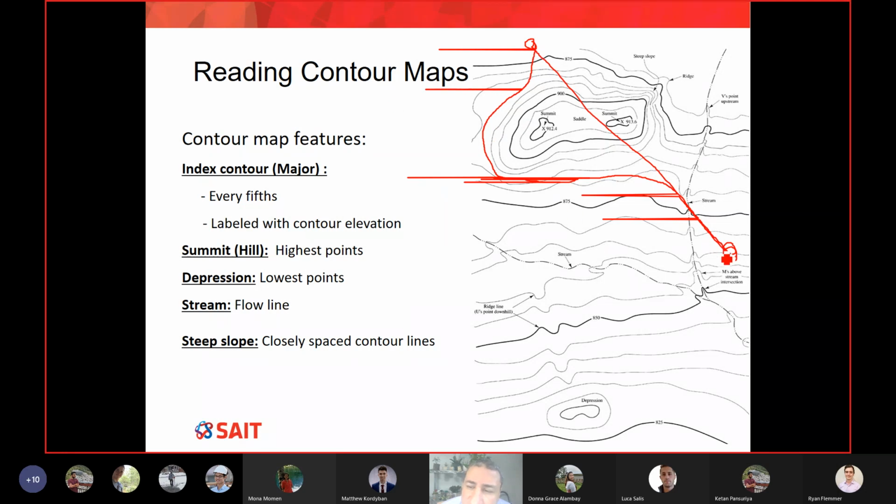So you can imagine that really the best idea is to avoid the topography, because we can see there is a kind of mountain here, and go around. Also remember, when we move parallel to the contour lines, I'm asking you, what is the slope? If I move parallel to the contour line, is it the same? I'm asking about the slope. Do we have a slope if I move this way? The elevation is the same if you move along the same line, which means there is no slope. That means the slope is 0. So the minimum slope is parallel to the contour line, while if you move perpendicular to the contour line, the slope is maximum.